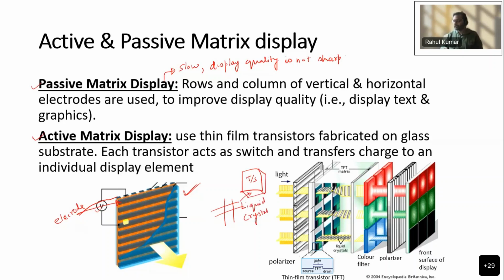Okay, liquid crystal is filled inside this glass tube, or you can say glass cell, and you have the transistors fabricated on the glass substrate. So transistors act like switches, and they will turn that cell on and off.